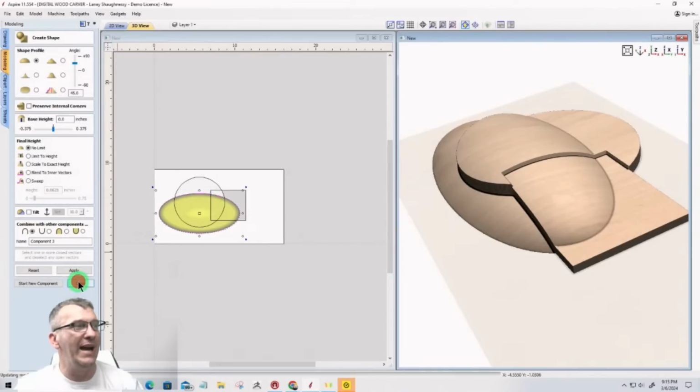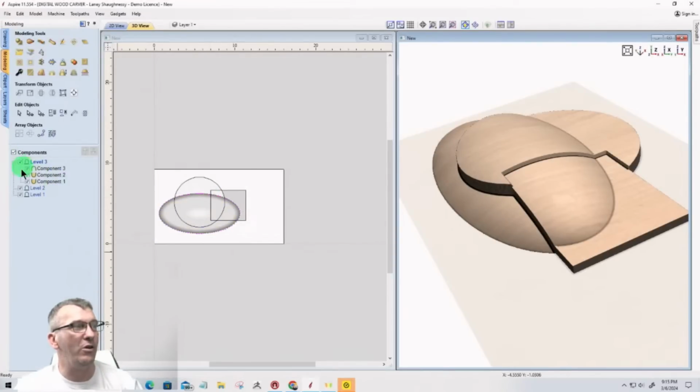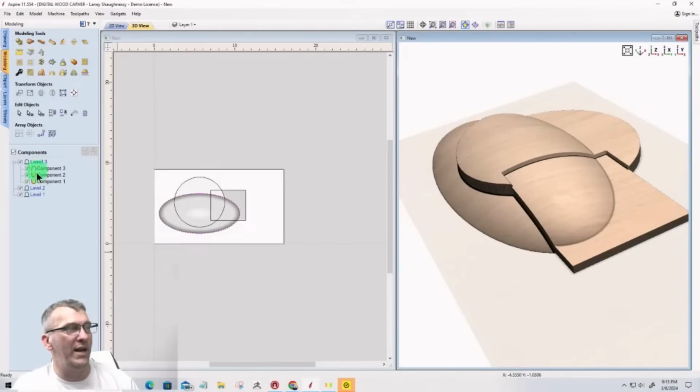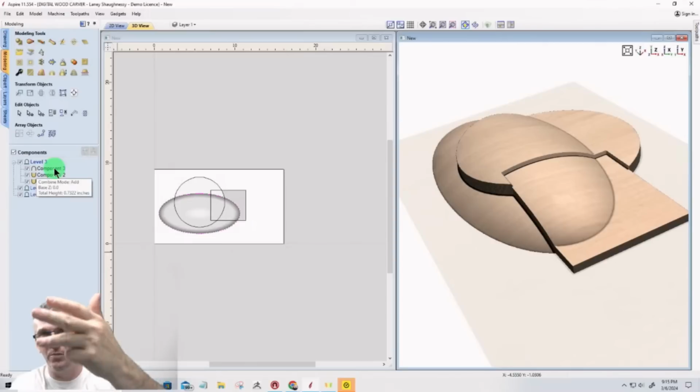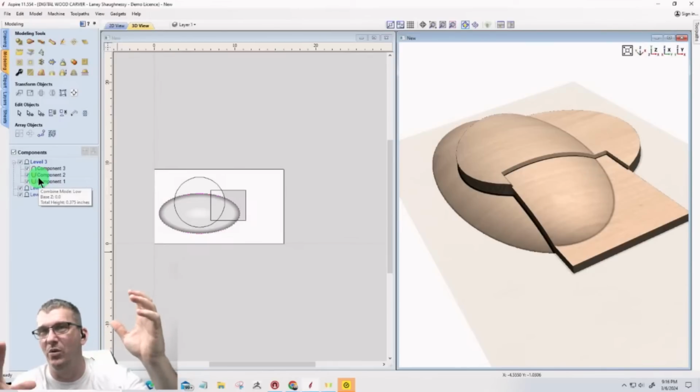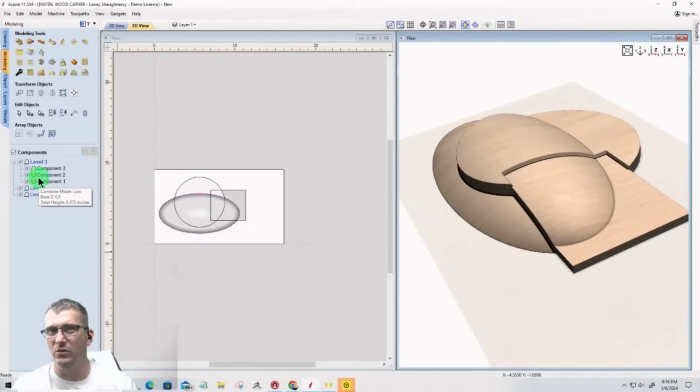If they're all on the same level, I can't really manipulate it that way. I can't get it to do that because no matter what, when I change the combine mode, add, subtract, merge, merge low of a component, if I'm on the same level, then it's going to change that combine mode for all, how it combines with all the components in the same level.